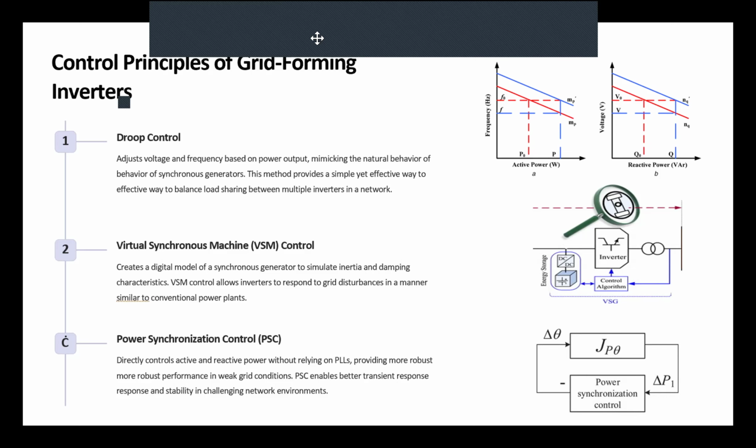It basically, that's correct. Now, what would change in the control system? If you remember the control system that we had for the grid following. We had the PID control, and then we had the PLL, and all those stuff together would control our situation in grid following. Now, in grid forming, as you said, we are basically mandating the state of the system at the terminal, so we're mandating the frequency and the voltage. Now, what difference we should make in the control system based on that one little change?